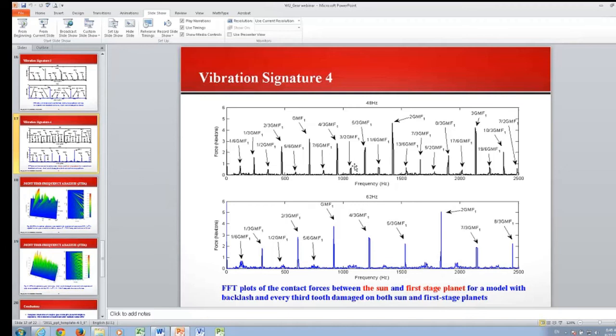Recently, in 2010, GE introduced a concept which is called sideband energy ratio. What they did is, for example, they add the six small sidebands near the gear mesh frequency 1. So now we don't have too many of these small peaks.